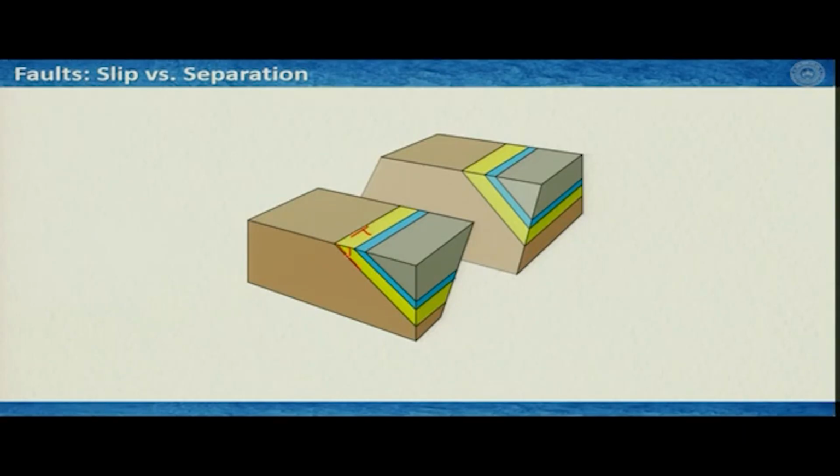And if this rock block is displaced by a normal oblique slip movement, then we know that this would be its strike slip component and this would be its dip slip component. So, I just write strike slip, this is dip slip DS and this is NS, net slip.